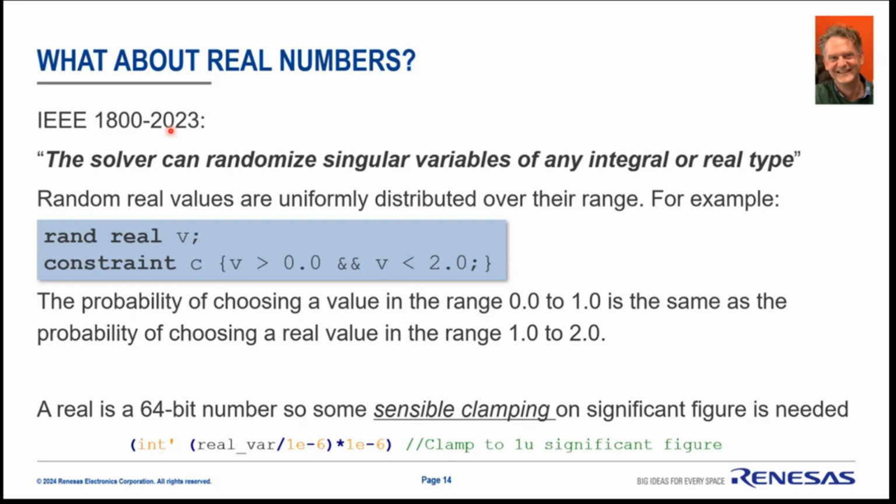But I think the point at the bottom here, which I might ask Peter to explain with a bit more detail, is to say that you have to be careful about the numbers that are generated because of the resolution or the precision of your analog solver. Yeah, so the digital can generate these wonderful 64-bit numbers, but there's no point in having accuracy below, say, microvolts, because most analog solvers have tolerances such that anything below a microvolt difference on iterations is ignored.